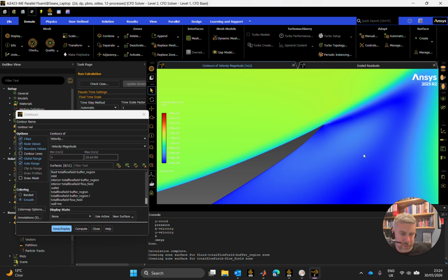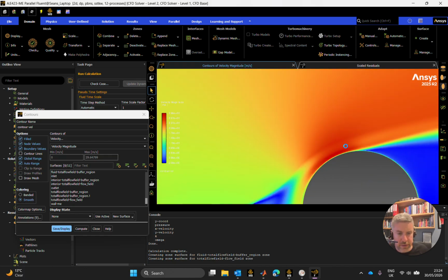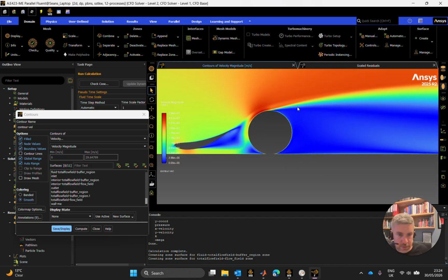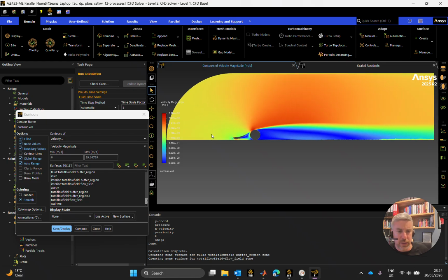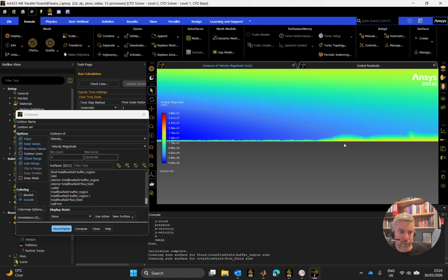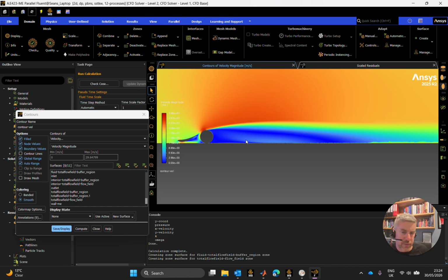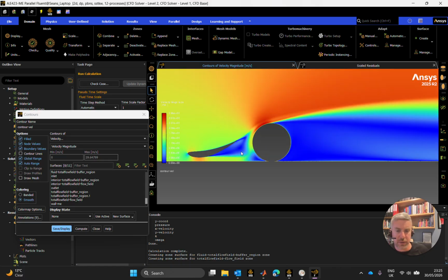Seems to be maybe some level of recirculation here, which no doubt is being contributed by the spinning of this wheel and tire, and then of course the big zero velocity or low velocity region right in behind that wheel. We see that wake coming off. Again, we have a rolling road here, moving road, and these sort of reactions here we can't really rely on because we're going to have a car body and a floor to work with here to treat this airflow to continue on. Okay, but nonetheless, very interesting looking contour, especially what we have in here.